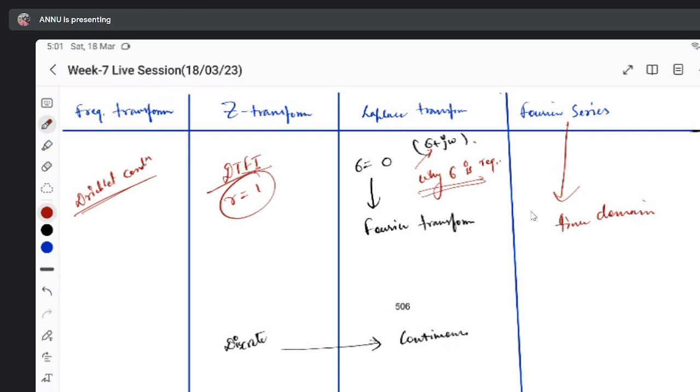So Fourier series, first we are seeing whether the signal is periodic or not. If it is periodic, then we are writing it in terms of harmonics of sine and cosine. So we are breaking it down to visualize it more clearly, and we will have some properties of that. So Fourier series is not a transform; it's just a representation in the time domain itself. But if you see it like a transform, then it should have some effect in the spectra. For the better analysis of spectra, we do the Fourier series.